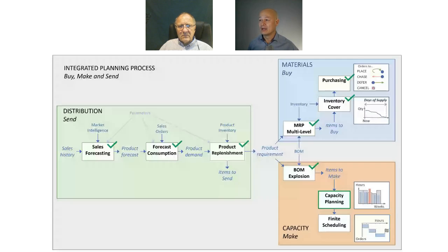different runtime. The way maybe we'd suggest handling that is, in order to do a run, we need to have a routing with a specific work center and a specific time for that item or that part to run on that work center. So we'd recommend having some primary work centers, but then run the system and see what the result is. And if we find that in the plan before we've executed it, in that what-if scenario, there's a work center overloaded, then the planner can go back and switch some of the orders to the alternative work center and then run it again.